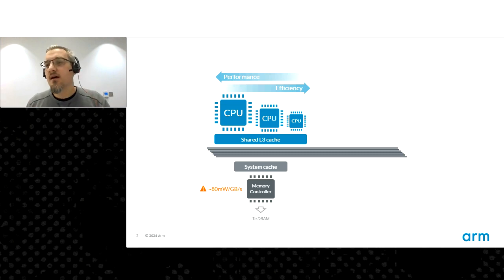You will see high-end smartphones being advertised with 80 gigabyte per second peak bandwidth capability. If you do the maths and work out how much power that's going to use, that would be 6 watts. You couldn't sustain that peak bandwidth every second throughout your game. So high-end devices with those very high bandwidth numbers give you small periods of burst bandwidth within a frame.